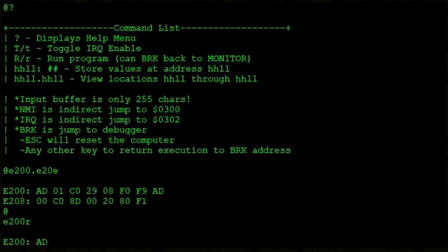What I've set it up as is I took an audio file and put it into Audacity and converted the sample rate. Instead of having 44,100 samples per second, I changed it to 11,520 because I'm running a serial port. It has one start bit, one stop bit, and 8 data bits, which makes 10 bits. So if I take the 115,200 baud and divide that by 10, I get the 11,520 bytes per second sample rate that I need.